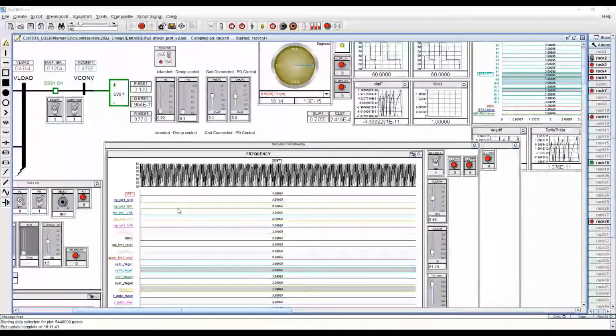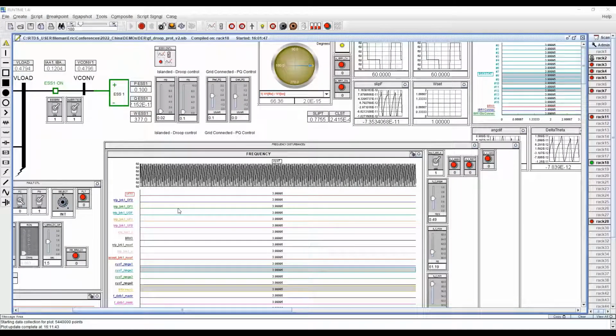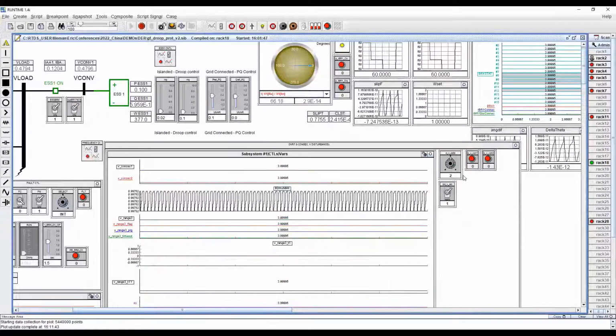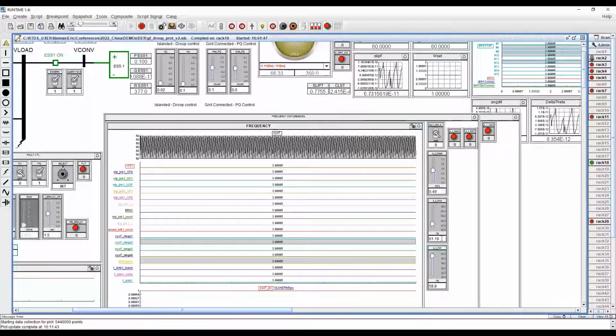The next scenario is on frequency disturbances within the continuous operation region. Let's first set this switch to 0, and in this case we'll need a voltage disturbance as well. So we're going to set this to the third scenario and with voltage disturbance. And then the minimum frequency here we set to 58.8 Hertz. Okay. Now trigger the event by pressing the push button here.